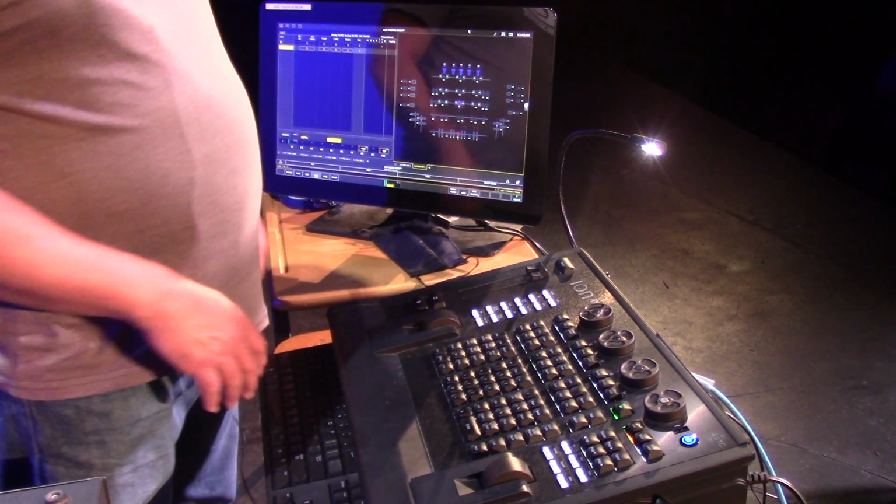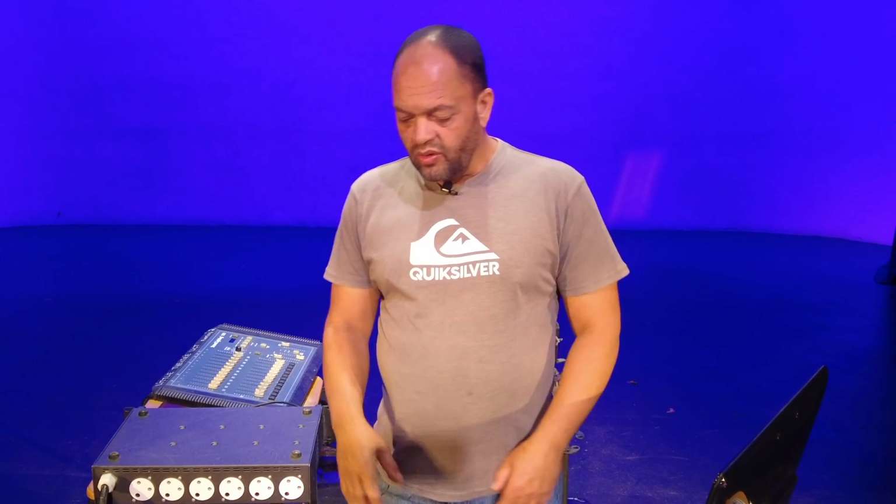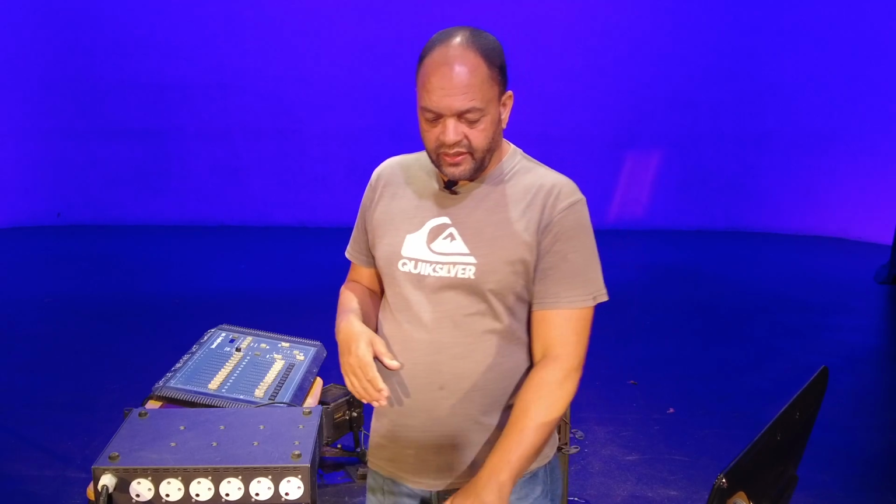You get an automated desk, you get automated equipment and everything. Basically, the principles are still the same. You still need your information to go from lighting desk to dimmers to your units. The only difference here is that with moving lights and with LED lights, there is no dimmer needed. So now the unit basically needs power, which is 220 volts again, and then just needs information between the desk and your actual unit.